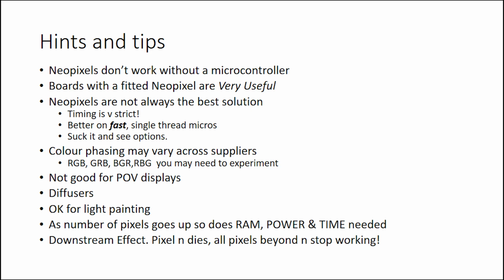Different suppliers, as I say, one supplier's red might be another supplier's green or blue. So it's worth taking them and building a very, very simple circuit just to control one NeoPixel to see how it works and play with it, make it work and get used to the colours and get used to the brightness, because they're bloody bright things. The new ones in particular will have your eye out. If you say, oh, 255, I'll have some of that. And the next thing, it's like when you look at somebody welding, you've got to go into the other room and make a coffee or something because you can't see anymore. So you'll get used to the brightness by playing with it.